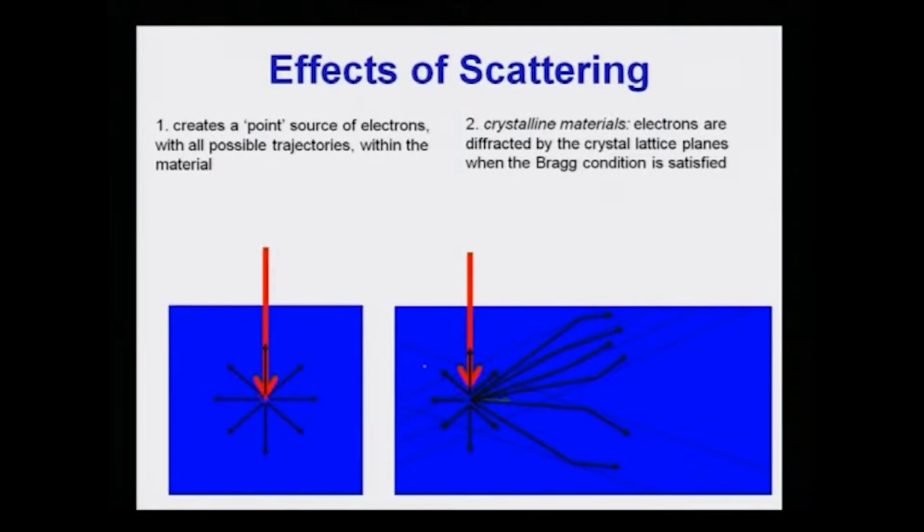As I said in the last class, if we change the beam orientation, we can have the channeling of backscattered electrons, at the same time the scattering of backscattered electrons inside the crystals, and this can give rise to black and white lines, which are basically Kikuchi lines. This is the reason for the origin of EBSD: the Bragg's law dominated or determined scattering of the electrons in the material.